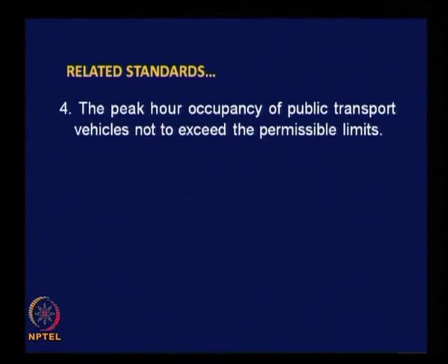Why have I not given numbers? Because over a period of time bus size may change, capacity of buses may vary, but our concern is about the capacity of the system. If you ensure that even during peak hour the capacity is not exceeding the permissible limit in any vehicle, then you are providing adequate capacity. Let us say 25 seated and 20 standing, totally 45 in a bus service. So at a particular point of time for any bus the demand should not be more than 45, that is the meaning. So this takes care of the possible changes in the system characteristics, still provides you with some number.